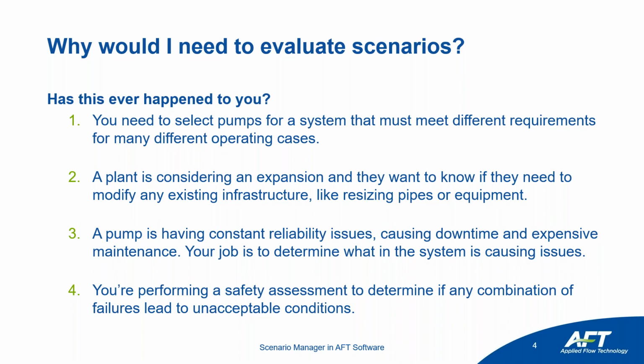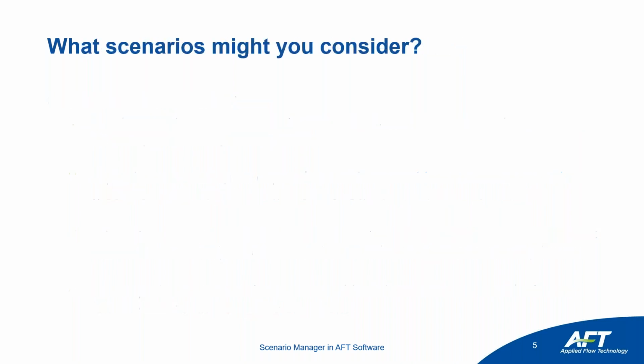So we can do sensitivity and explore a lot of different options and combinations to really determine our worst case scenario. And especially for things like transient analysis, where you're designing for surge pressures and extreme forces, you can base those other designs off of that worst case scenario. So those are kind of 4 example cases, but we can generalize them a bit further. And even more so, we can look at what other scenarios you might consider in your own system.